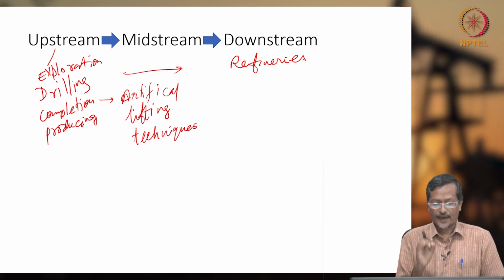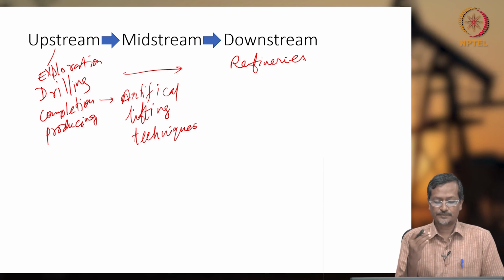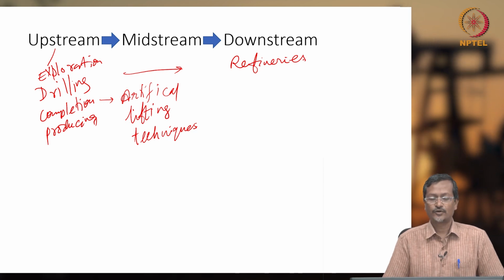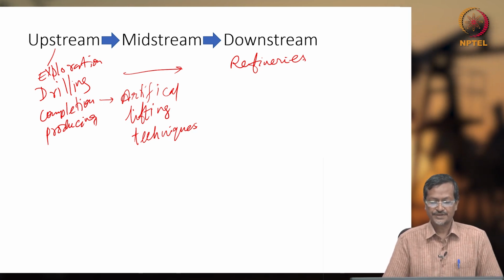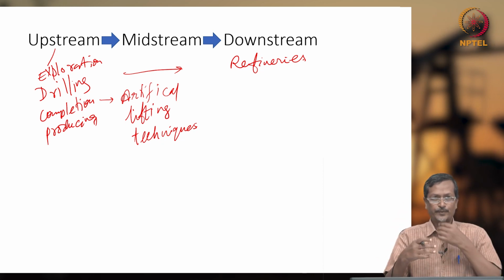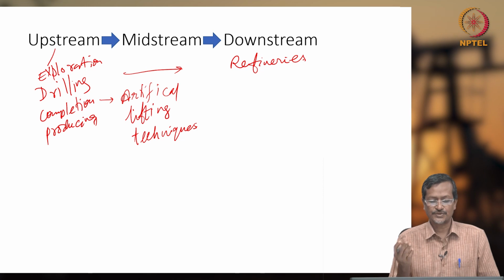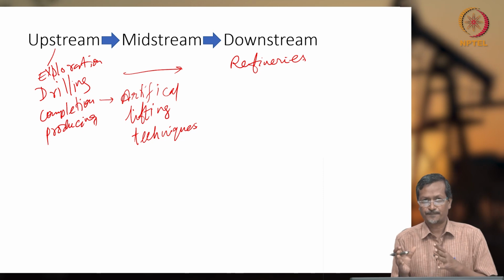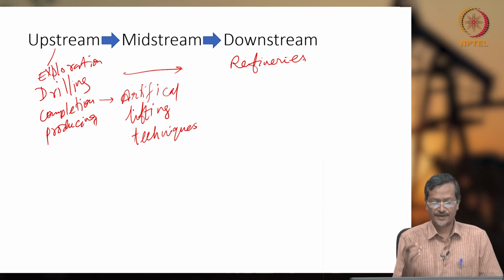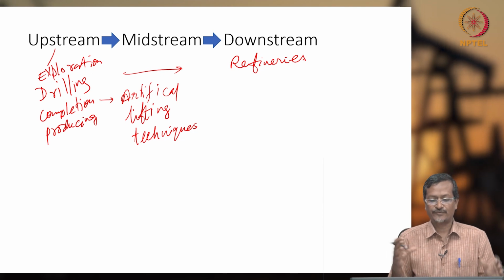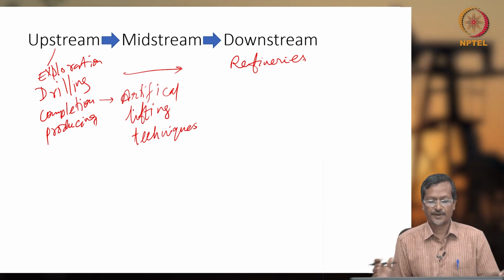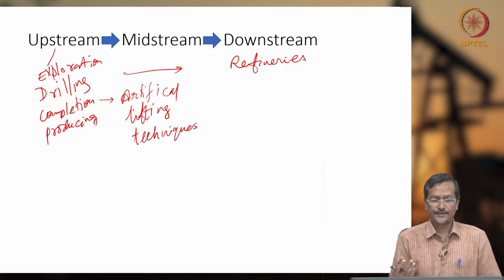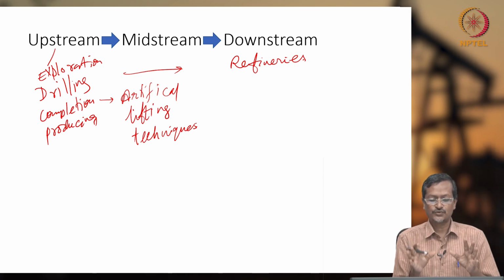When you are completing, actually you are making the wellbore. In the drilling stage, you are drilling a hole and it will be producing oil and gas. During the completion stage, the drilled wellbore will be producing, but that can be uncontrolled, and there will be several issues. So, during completion stage, you solve the issues and you make the wellbore ready for production. And what are the completion stages? Like cementing, putting pipe properly, fixing chemistry and other valve operating systems, you have to connect piping systems, you have to put artificial lifting systems, etc. Then once everything is done, you hand over the task to production engineers.